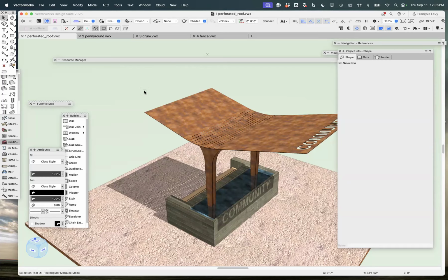To make a surface array, you need two things. I'll double click on this to edit it further. You need a base surface, and then you need the items that are being arrayed on the base surface. So let's look at that base surface, because that's usually where I'm going to start. In this case, what I have is a NURBS surface. That's one of the legitimate allowable surfaces that you can use for an array. We'll look at some other options a little later.